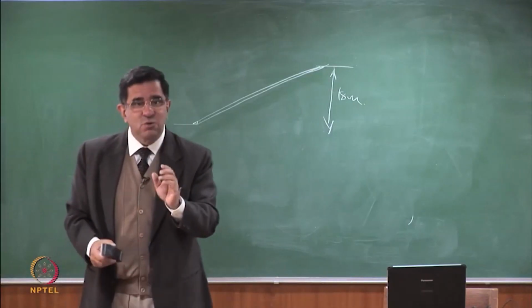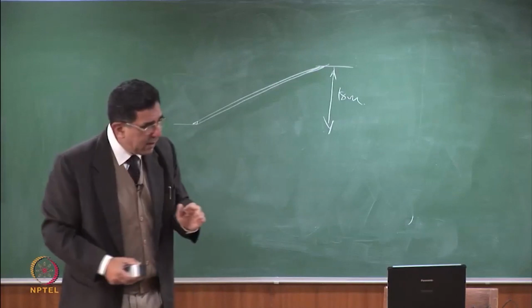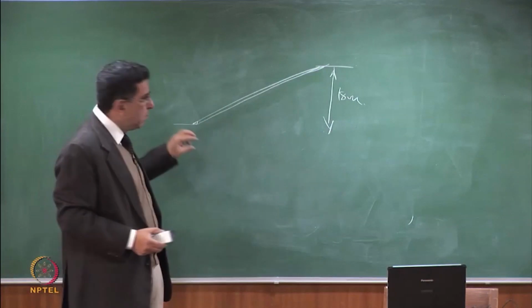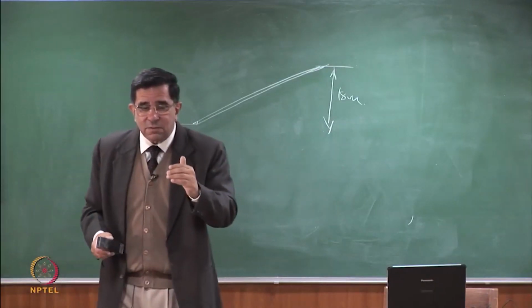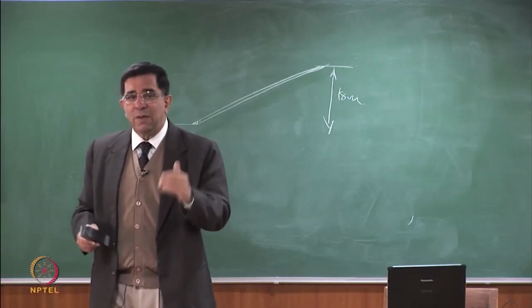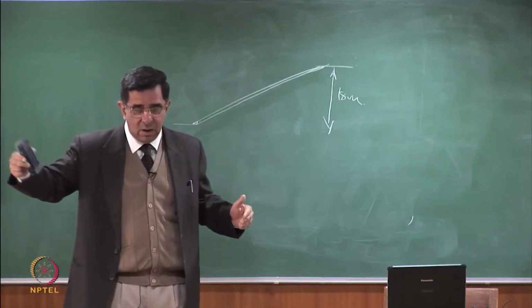Will the passive wedge give you better factor of safety or less factor of safety? Infinite slope assumes this is not there, this slope is just going down. The moment you have a passive wedge, it gives you some enhanced factor of safety. When does it become important? It becomes important when the slope length is not that long. It is still long, but not that long.